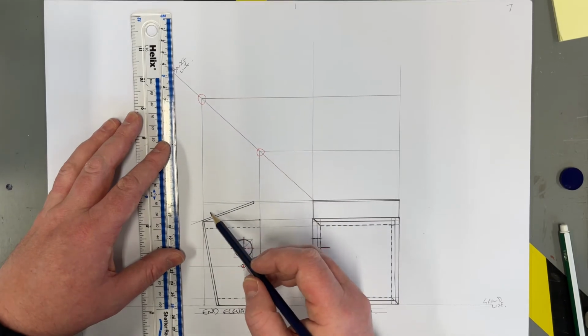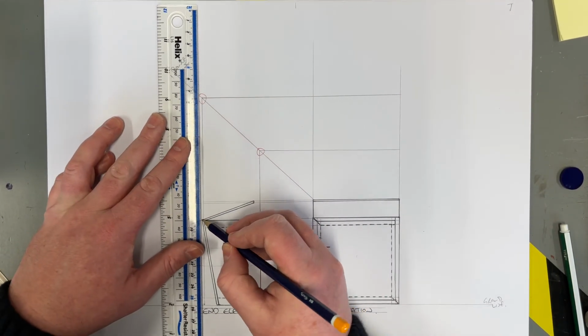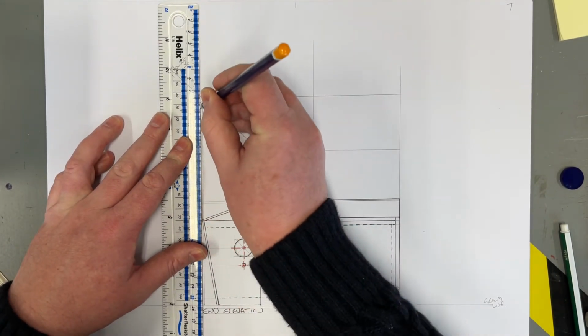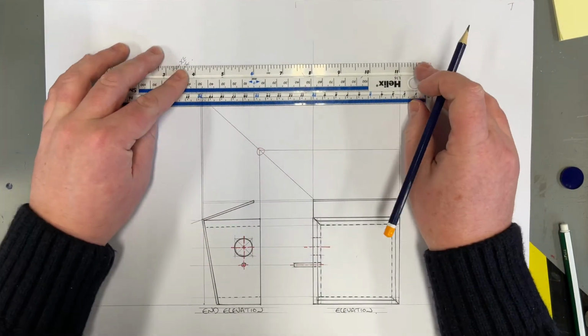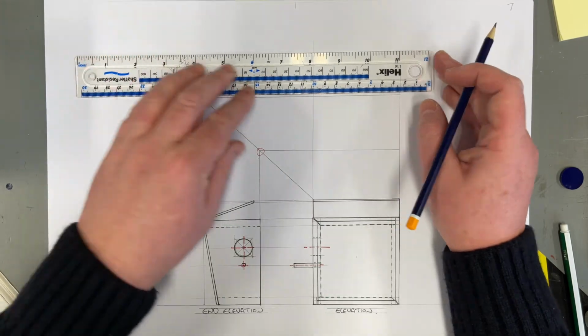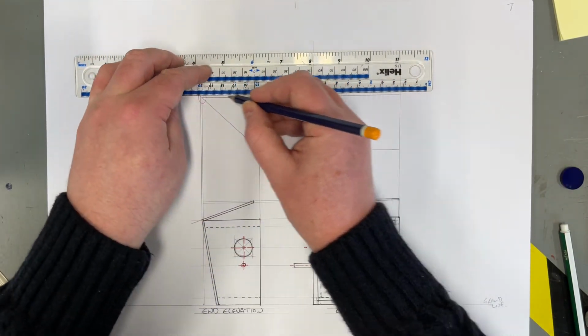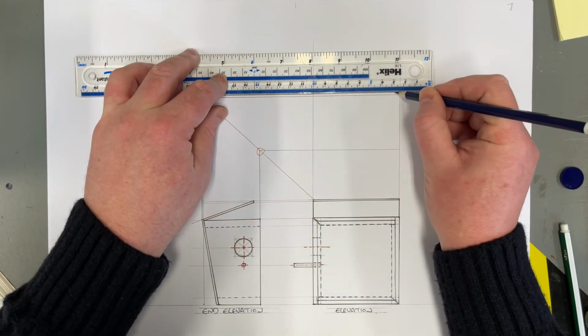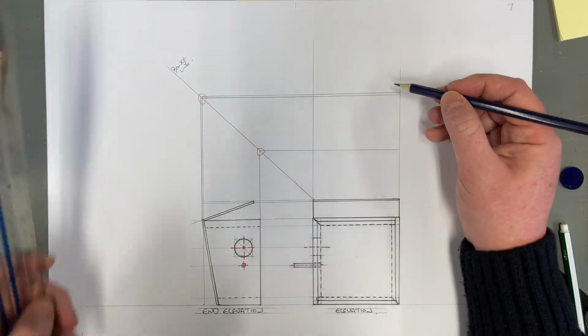Right, now, looking down on the object, we notice that we see the metal before we actually see the wood. So we know that we've got the back edge of the metal here. If we project that up also and across, we do have that little material thickness of 1 millimeter coming in. So we bounce that up too, and that shows us the thickness of the metal.